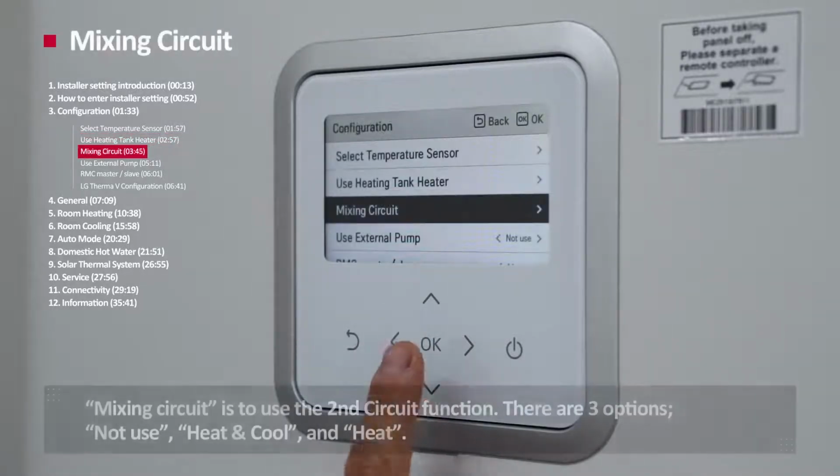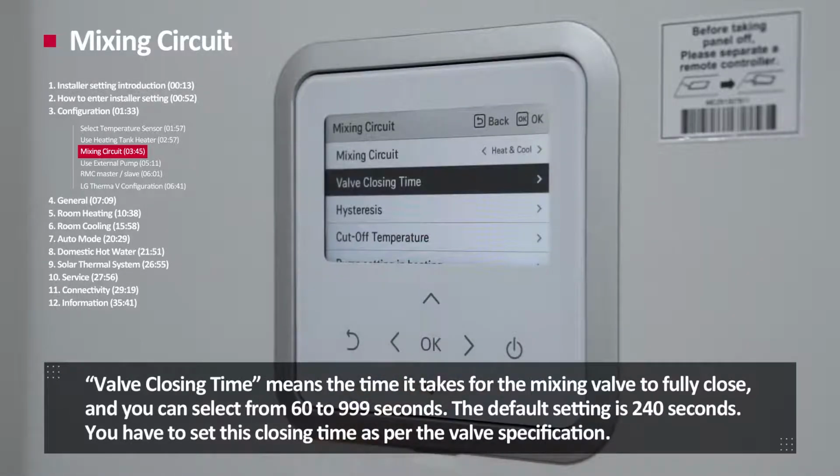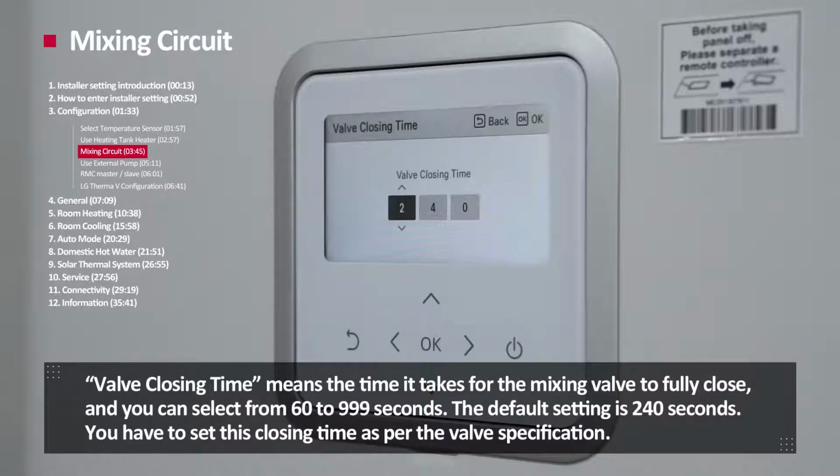Mixing circuit. Mixing circuit is to use second circuit function. There are 3 options: not use, heat and cool, and heat. Valve closing time. Valve closing time means the time it takes for the mixing valve to fully close, and you can select from 60 to 999 seconds. The default setting is 240 seconds. You have to set this closing time as per the valve specification.